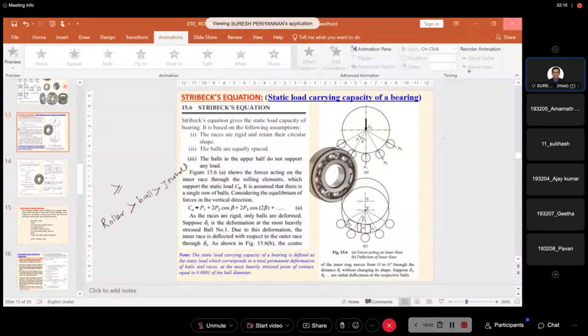See, I told you that based on metal to metal contact, you can define that. Which one has less contact? Ball bearing is point contact. Hence, will it develop more noise? When two surfaces are in contact under dynamic conditions, more noise will be generated. Hence, which one is it now? Ball bearing generates more noise. Now you might have understood.